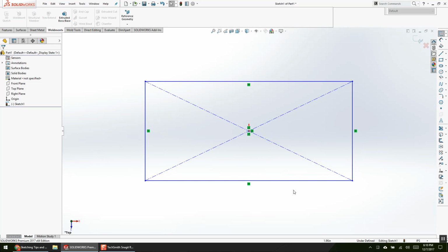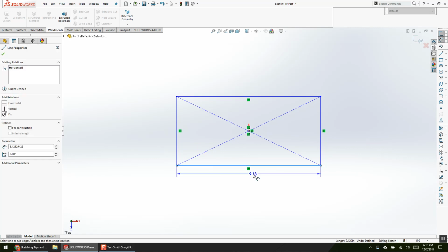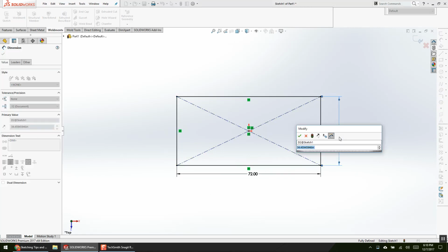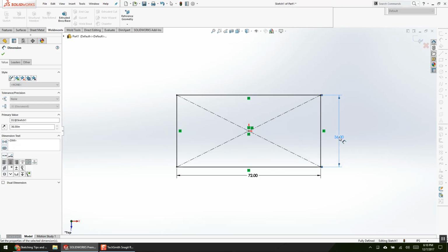So, for example, if I design this table and I say it's going to be, I don't know, 6 foot, and we all know that we can type in units, right? So I can do 6 foot by 3 foot. So I can type in 3 and the single quote symbol, which is foot. And when I hit enter, SolidWorks will convert it for me to 36 inches. I hate doing mental math. I actually don't hate it. I like mental math. But every time I've done mental math, the computer's always won. That's what SolidWorks is really, really good at.